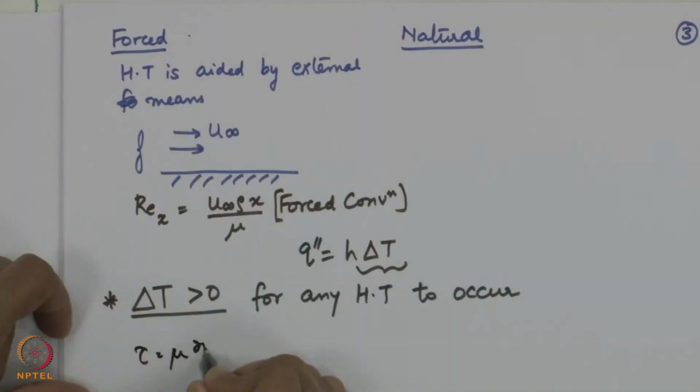Gradient in the velocity at the wall is responsible for the wall shear stress. This is caused by viscosity, correct? The temperature gradient at the wall is responsible for convective heat transfer, and this is caused by the fact that you have no slip, thermal no slip condition. So, there you see tau is equal to mu du by dy at the wall, y equal to 0, h is equal to minus k over some delta T dT by dy at y equal to 0.